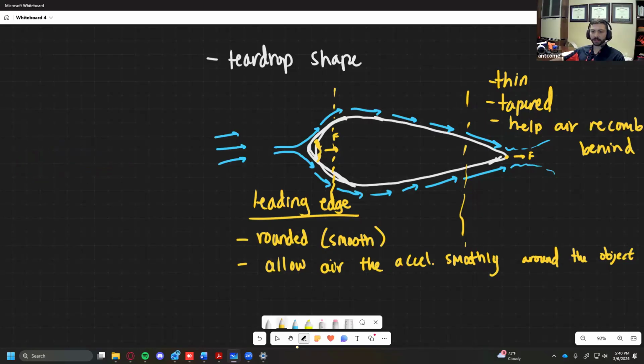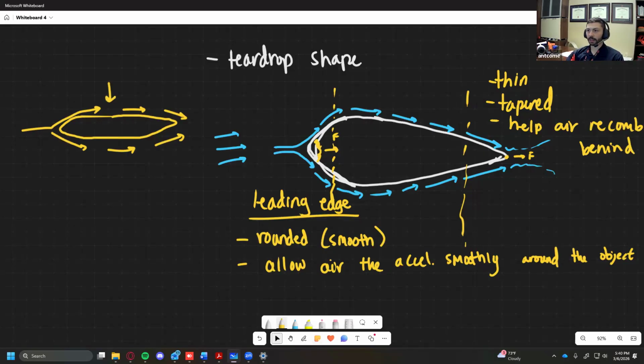Correct. If you had, let's say, just a spar or a structural component which was just involved in the flow, you could make that as streamlined as possible, very, very thin, something like this, so that this is the smoothest possible thing you can do because its job is to minimize drag and not care about lift. And so right now, since we're talking about drag, what you said is exactly right. This would be a better shape than just a teardrop. And yeah, a thin piece of plastic, or a very thin piece of paper, is obviously the most ideal case, right? You're barely splitting anything.